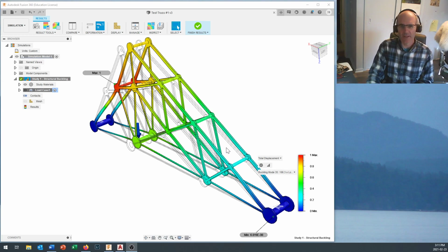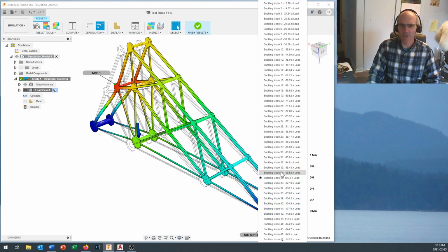And you'll notice that out here, we have very little buckling happening. Now, how hard would we have to push to cause this side out here to buckle? Well, there are all these different failure modes. And if for some reason it didn't buckle at 106 newtons, keep coming down and looking for the next positive failure. Here we go, buckling mode on my design. It's at 148.